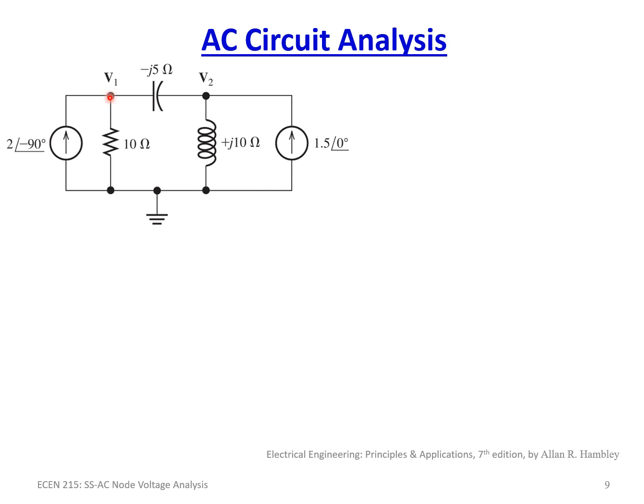You're starting here, and then you're just subtracting the node that you're leaving to, and then dividing by the impedance in question. Yeah, so let's go ahead and start that. So our first element is this 10 ohm resistor. So we have V1 minus 0. This is the other node in question. So it's just V1 divided by 10 ohms.